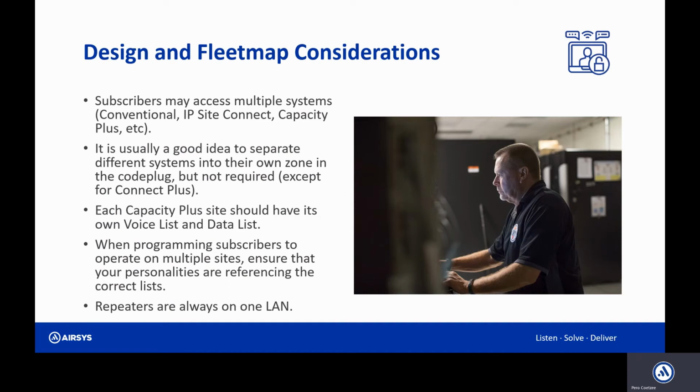So looking at the design and Fleetmap considerations, subscribers may access multiple systems. So you can have multiple different systems in your configuration. It can be conventional, IP Site Connect, Capacity Plus, single site or multi-site, etc. And it's usually a good idea to separate the different systems into their own zone. And although it's not required, it just makes it more clear, and that you don't call the wrong customer or the wrong user. So always separate them into the different zones,